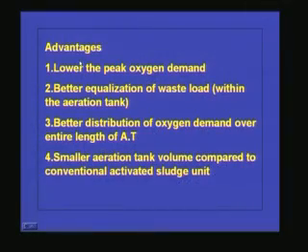The advantages of this tapered aeration system or step-fed system are a lower peak oxygen demand, because we are distributing the flow, better equalization of waste load within the aeration tank, better distribution of oxygen demand over the entire length of the aeration tank, and a smaller aeration tank volume compared to the conventional activated sludge unit.